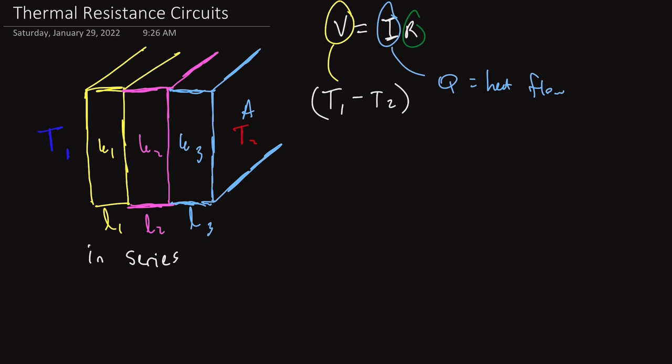How can we rearrange this equation so that we can begin to model the way in which thermal energy moves through a system via conduction? You do that just by dividing some terms around and doing some algebra. What you ultimately arrive at is the following: Q, the heat flux in our system, is equivalent to T1 minus T2, quantity divided by R. If we were looking at a single resistor, that would be it. It would be a pretty simple process, because we'd only have one resistance, and that would be R. Specifically what we want, though, is R total.